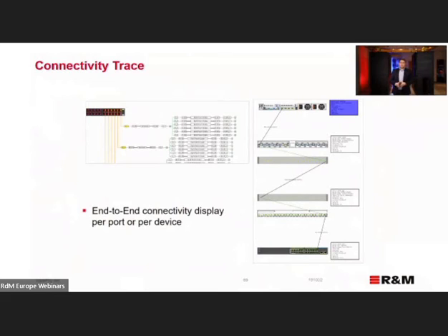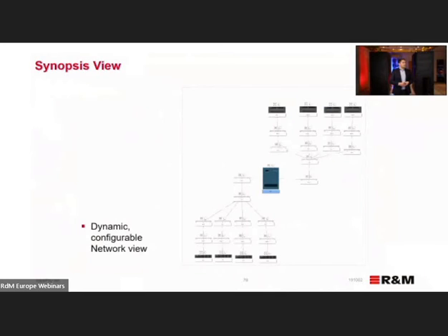And the application is focused on documentation. So here we can document all the details about the connectivity. So we will know how devices are connected to each other and what is in between them, eventually some panels, some other devices. So by selecting the port on the end device or on the outlet, the application will present us in a graphical way what is the path for the data, for the connection.